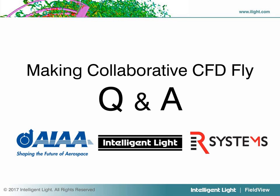Okay, another question is, could you explain a little bit about the difference between an XDB workflow and using remote graphics on the system? Right. Yeah. So with this XDB workflow, we created the extracts all in batch. So FieldView resided on the remote systems at our systems, and then we created FieldView FVX programs, and we ran FVX on the queuing system on those remote systems. So within that, the output from that job would be FieldView XDBs.